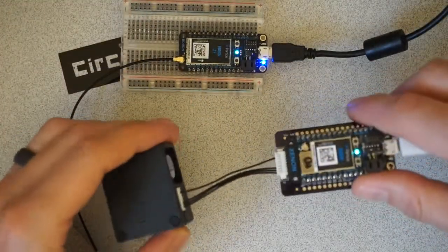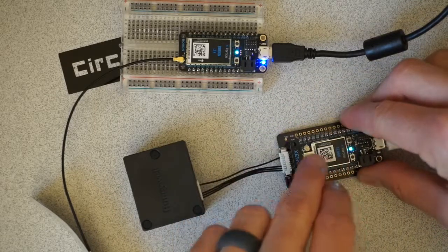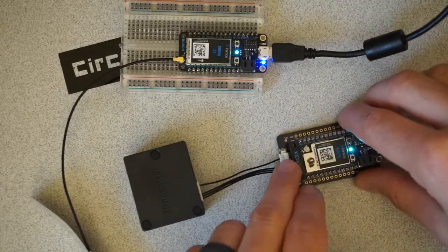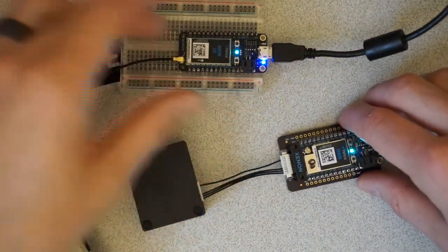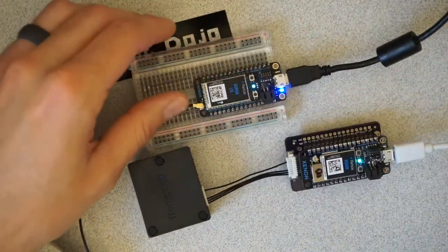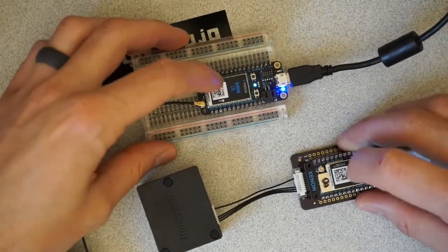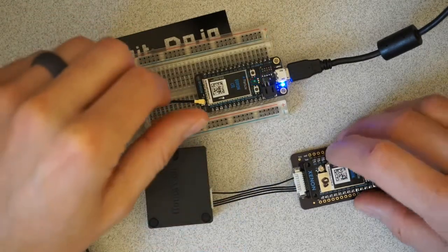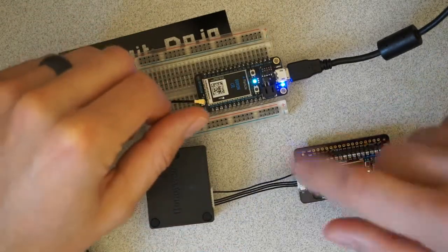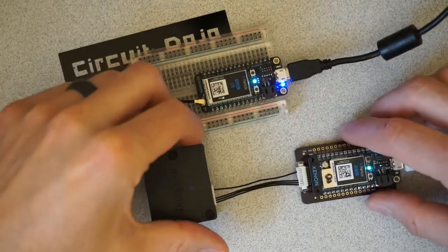So whenever this guy takes a measurement, it will send a low power message over the OpenThread protocol to this guy. Then it'll be forwarded on to the internet. As far as I know, these guys use a UDP connection to the internet, so it's not as reliable as TCP, but there's a lot less overhead.